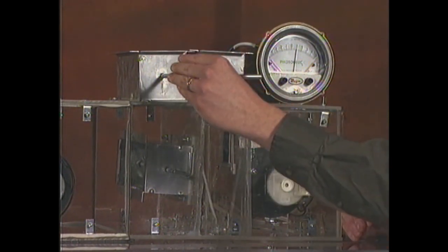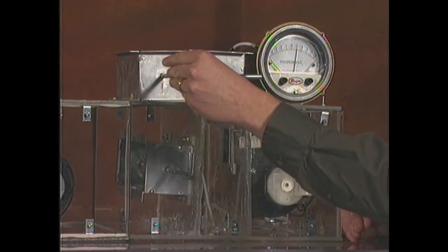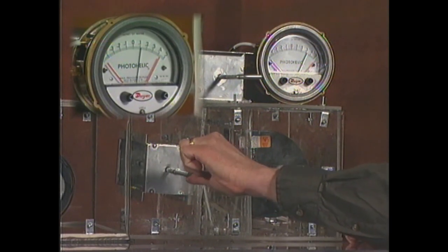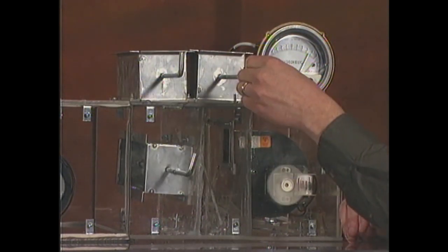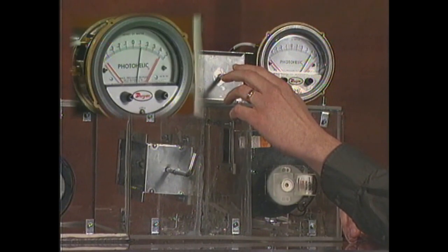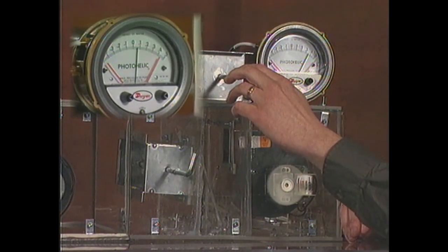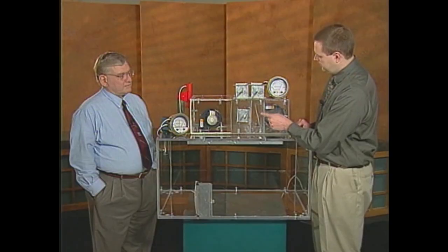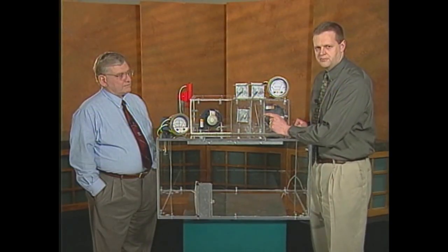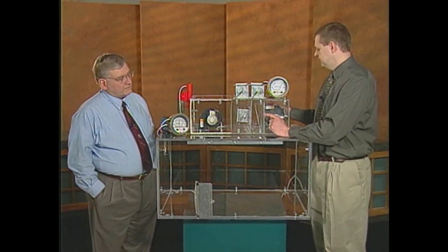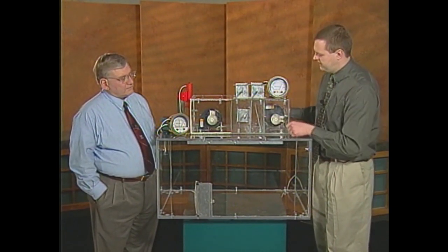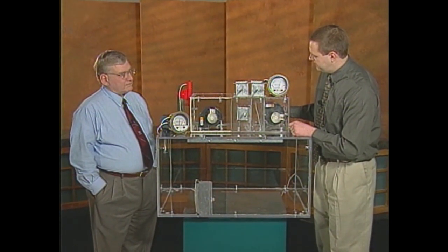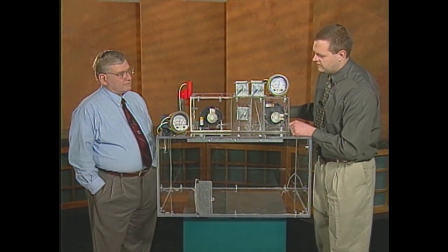So if we go to economizer mode, open up the outdoor air damper, close the return air damper, what happens is our building pressure is going to go up a little bit, so we're going to open our relief damper to get building pressure back down. We also increase the return air plenum pressure quite a bit, so we're going to slow the speed of the return fan down as we get back down to its set point.